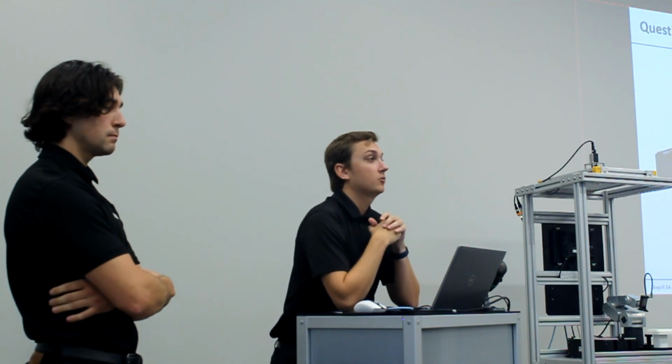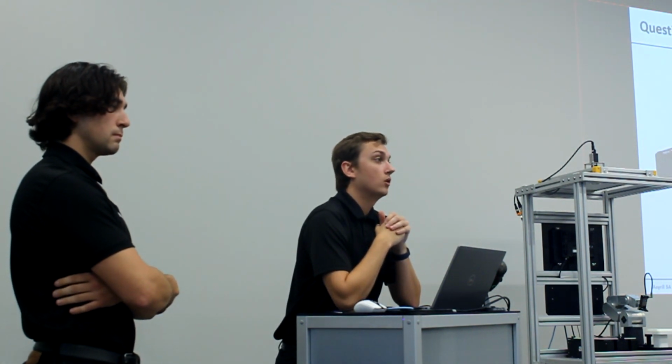With 2 robots, the hand-eye calibration only provides part coordinates to 1 robot reference frame. So if you wanted to use 2 robots, you would have to translate the part coordinates into the second robot's coordinate frame. So the easiest way to do that is, sometimes you don't do the robot calibration. So instead, the I+ system is just giving you the default robot coordinates.